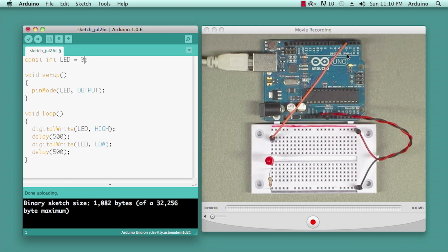Pulse width modulation is basically the Arduino can be put into a mode using a special command where it turns the voltage on and off to whatever pin has a tilde incredibly fast. And it can change the duty cycle, how long it's on versus how long it's off, to send what looks like the equivalent of 0 volts, or 5 volts, or 3 volts, or 2.5 volts, depending on how we define the right command for that individual pin.